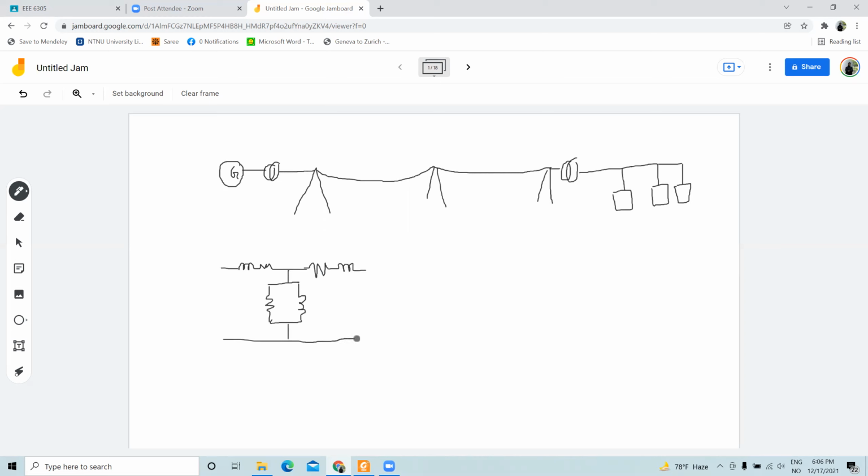And in a very simplified model, as the current which is coming through the primary, most of the current is basically going through the secondary, and a very small amount of current is actually flowing across these shunt components. So you can basically ignore it for the time being, and you can model the transformer in a very simplified way, like an inductor and a resistance, like this.